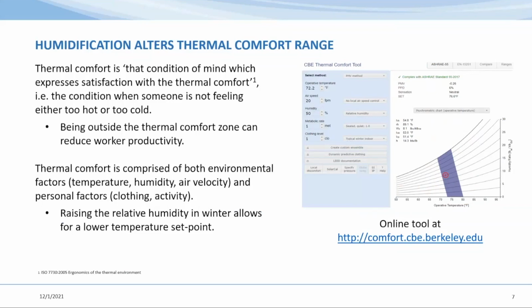So if we can keep that in mind and condition that air specifically for people, that's obviously an aspect of temperature, but also humidity. In the winter, colder temps feel warmer when humidity is higher. Likewise, in the summer, when humidity is lower and it's high temps, it feels better on you because you're able to dissipate heat. So with that, most room temps are 68 to 72 degrees Fahrenheit, and back to that 40 to 60% can really impact the thermal comfort.